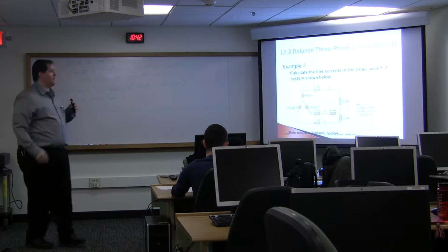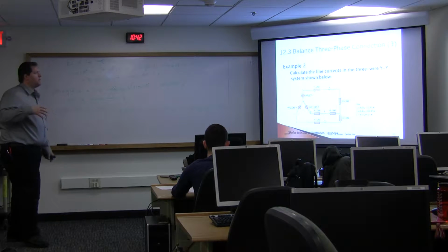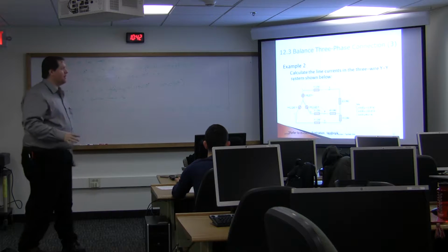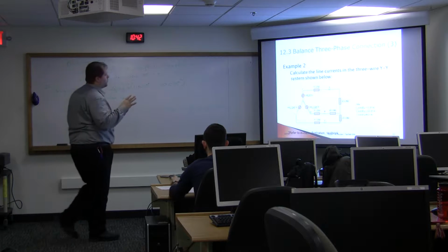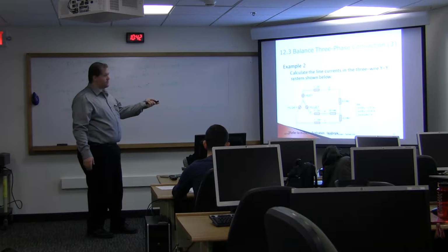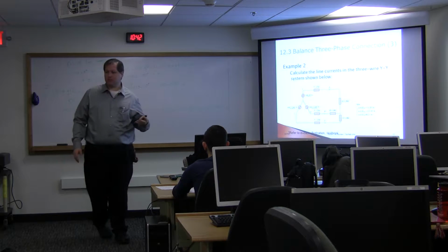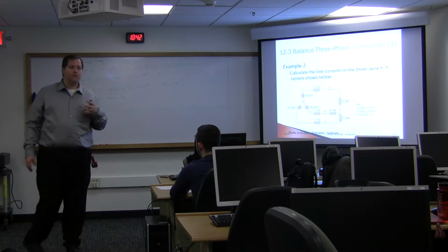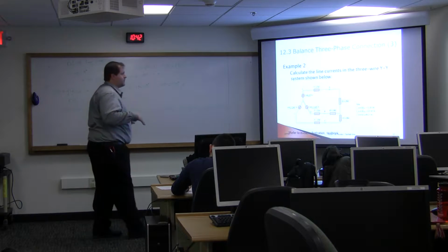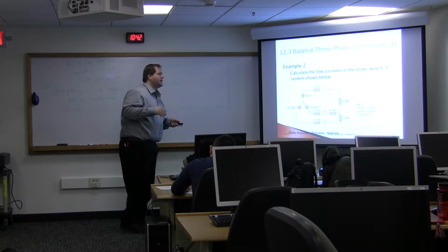So, just to wrap things up today, when we're talking about these systems, I said terminology does matter. And so we've described this leg, in the case of the supply, from neutral to point A, as a phase voltage. That is the voltage of one of those supplies measured independently, if you will, to the neutral point.